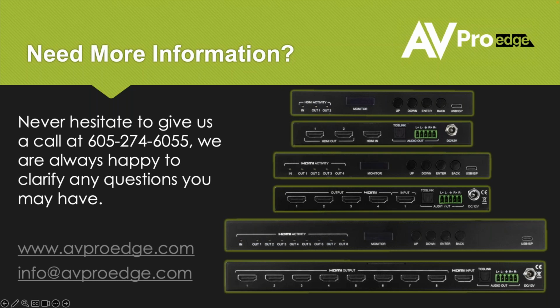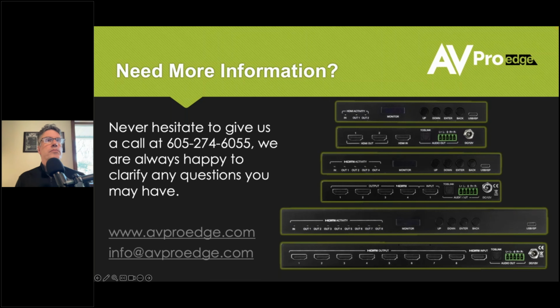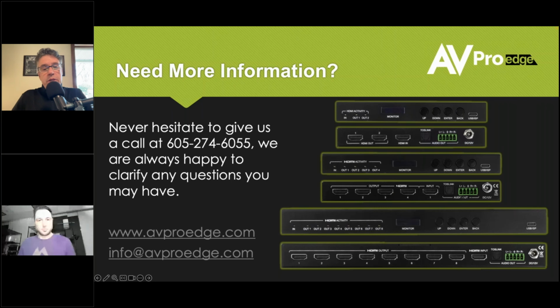So there are 2 questions that came in, one from James. He said, can you use any of these devices as a way to extract audio from an Apple TV to a secondary zone? Yes, absolutely. With the Toslink, you can take the full surround out through that Toslink to a second zone. If you need to take 2-channel out, not a problem whatsoever, but you are going to have to set the EDID for 2-channel, and your Apple TV is going to send 2-channel to the analog out.